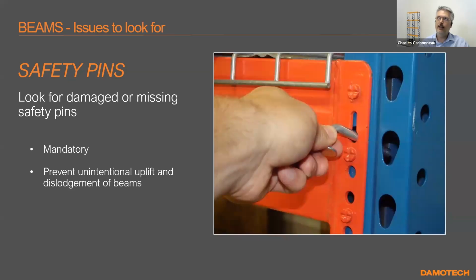They're designed to withstand at least 1,000 pounds each of uplift. But since you're raising one pallet on one side, it's basically just that side which will have that uplift. Sometimes when we inspect, because of vibrations, they're not totally come off, but they're unhooked. Oftentimes we'll recommend just putting a bolt and a nut in there and forgetting about it. It's going to be forever. Now, the choice of the diameter of the bolt has to be right, so please have someone look into it.